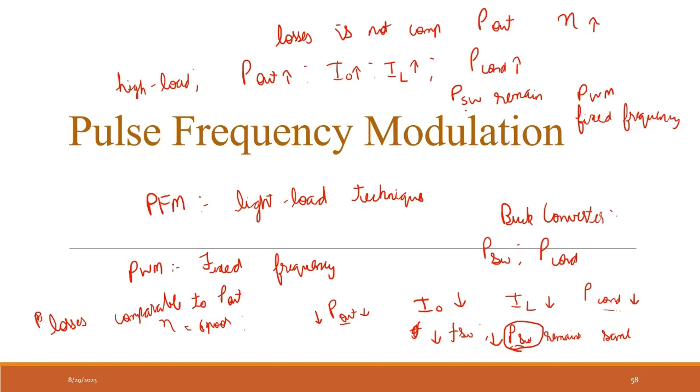Sir, in high load condition also, when we are switching, since the load is high, the magnitude of current reaching for each switching is higher. So switching loss will also be higher in high load condition. Or compared to conduction loss, is it somewhat inferior?